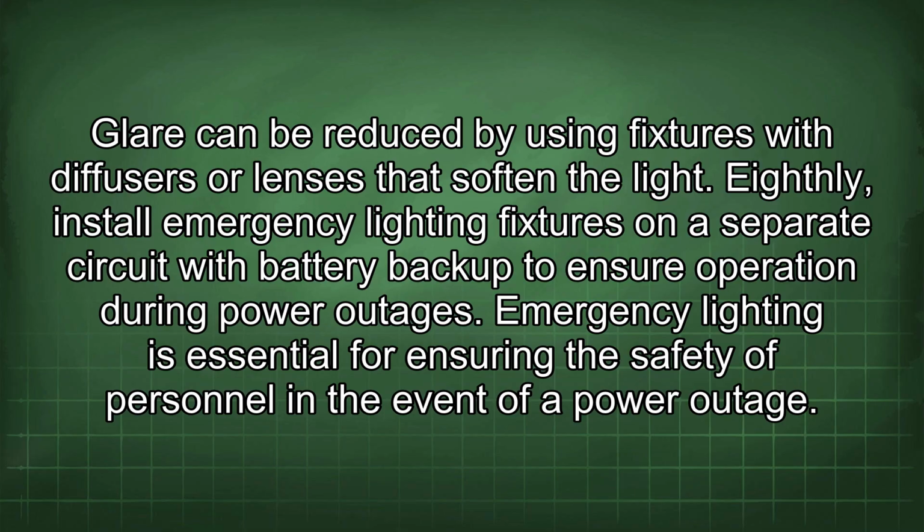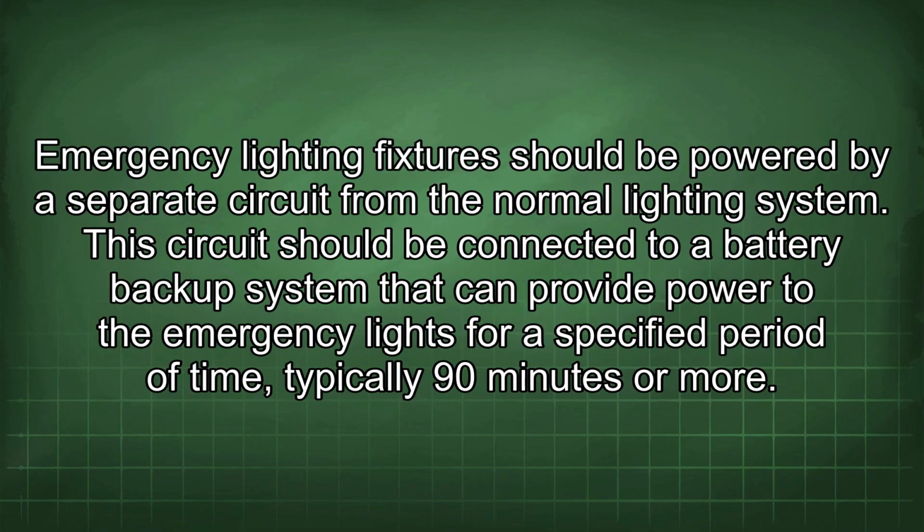Eighthly, install emergency lighting fixtures on a separate circuit with battery backup to ensure operation during power outages. Emergency lighting is essential for ensuring the safety of personnel in the event of a power outage. Emergency lighting fixtures should be powered by a separate circuit from the normal lighting system.